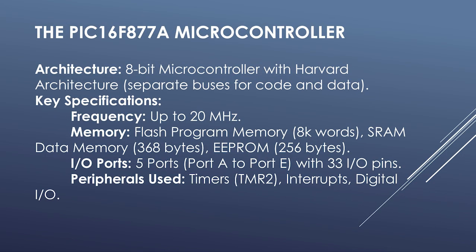PIC16F877A microcontroller. The PIC16F877A is an 8-bit microcontroller that follows Harvard architecture, which means it uses separate buses for program instructions and data. This improves processing speed and efficiency. It can operate at a clock frequency of up to 20 MHz, making it suitable for many embedded applications.